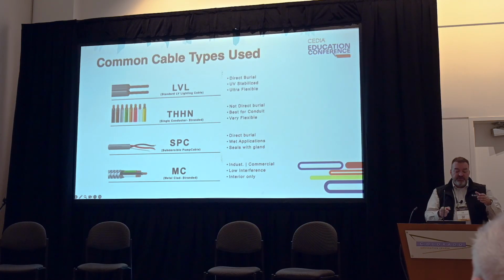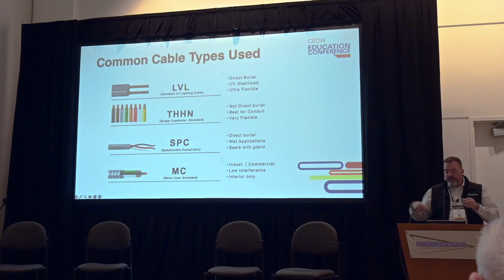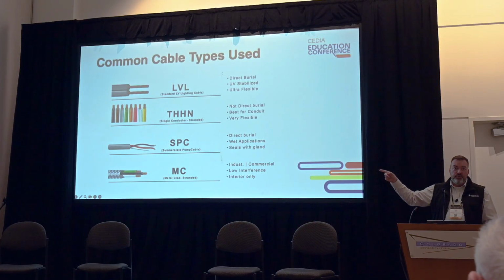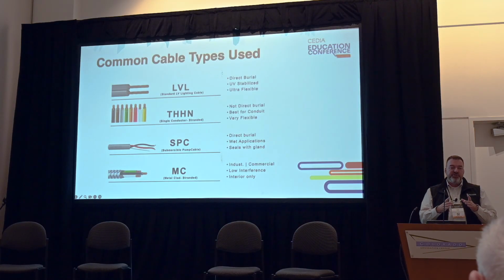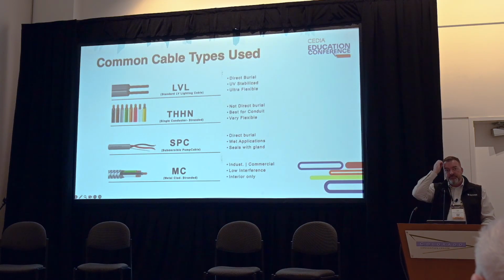If you don't seal up those ends, you can get a vacuum effect in your well lights or in your underwater lights. As they heat up during the night, the pressure will increase, and then as they turn off, they cool down, the vacuum pulls air into that fixture. And if you have that open end, open to the dirt or wet soils, it's going to pull moisture right up that line, and you'll see moisture inside. Most of the time you see well lights or in-grade lights that have water in them, it's not from leaking, it's from not sealing off those ends of those cables very well.